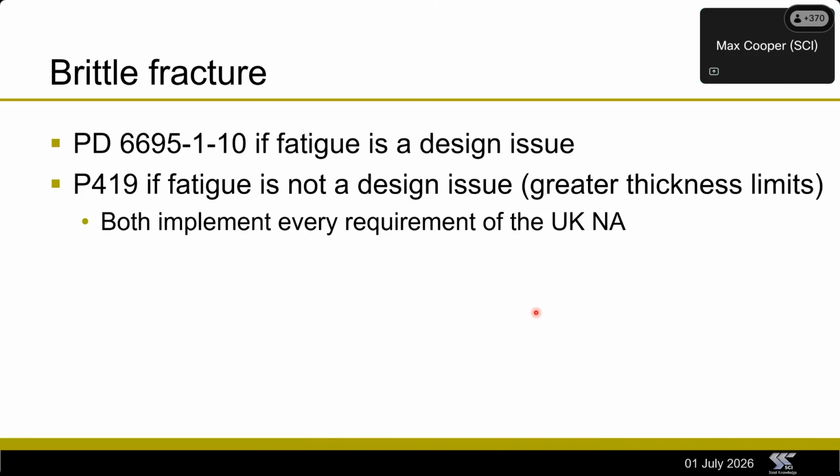So for brittle fracture, if fatigue is a design consideration, you should be using Eurocode and the UK NA. If fatigue is not a design consideration, which will obviously be the majority of steelwork in the UK for buildings, we suggest you look at P419, the SCI publication. That applies all the UK national annex rules, but it removes some of the fatigue crack growth, and that gives you some increased thickness limits that you'll find are very beneficial. So that's a topic for another presentation, but that's a very helpful publication.